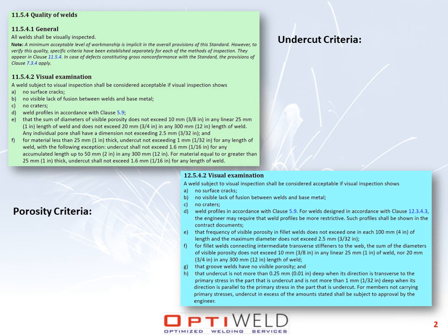Knowing inspectors enjoy a challenge, things get interesting in that there is not one, but two sets of differing acceptance criteria within this standard. Clause 11 in green is for statically loaded structures like steel fabrications used in a building. Clause 12 in blue is for cyclically loaded structures like the steel fabrications used for bridge construction. We will see that Clause 12 is more stringent in permitting less of these discontinuities, partly due to more concern for fatigue failure in cyclically loaded structures.